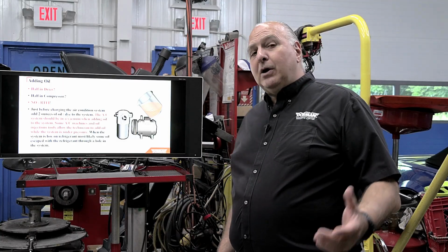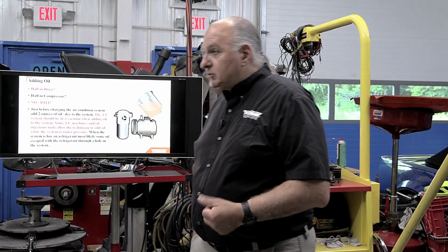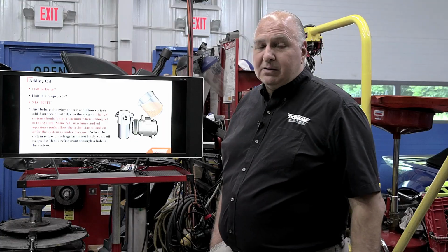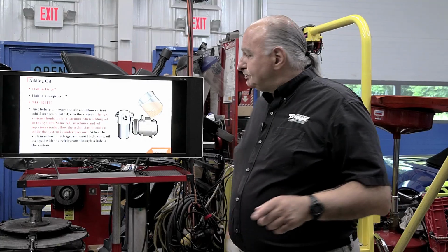So I said, well, take that thing, open it up, and we have these little squeeze bottles, or a turkey baster. We have both. You put the measured amount of oil in, you squeeze it in the opening, you let it go through, and now it's in the condenser. It's in the receiver dryer. And then he goes, well, how do I know how much to put in? I said, well, RTFI. You see the computer in your bay right there, or the tablet? All the info's right there. You just got to look it up. And he looked it up and goes, you know, I didn't realize that. Well, thank God he hadn't done many AC jobs, because that's how people's AC systems get ruined, okay?